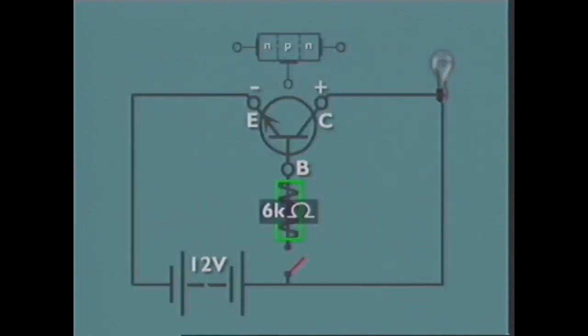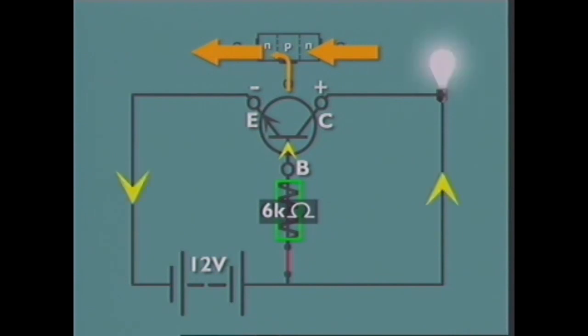In this circuit, this NPN transistor can act as a switch. If the control switch is open, the depletion layer at one PN junction is blocking current from flowing through the transistor and driving the load. With a closed control switch, a small current flows through the emitter base PN junction. The base has only a limited number of charge carriers, so extra ones flow across the emitter collector PN junction, letting current operate the load.